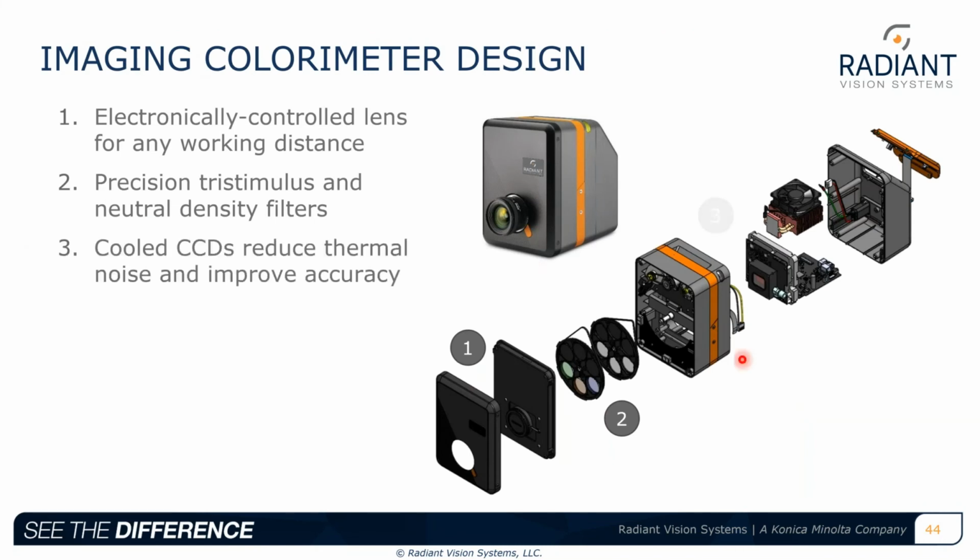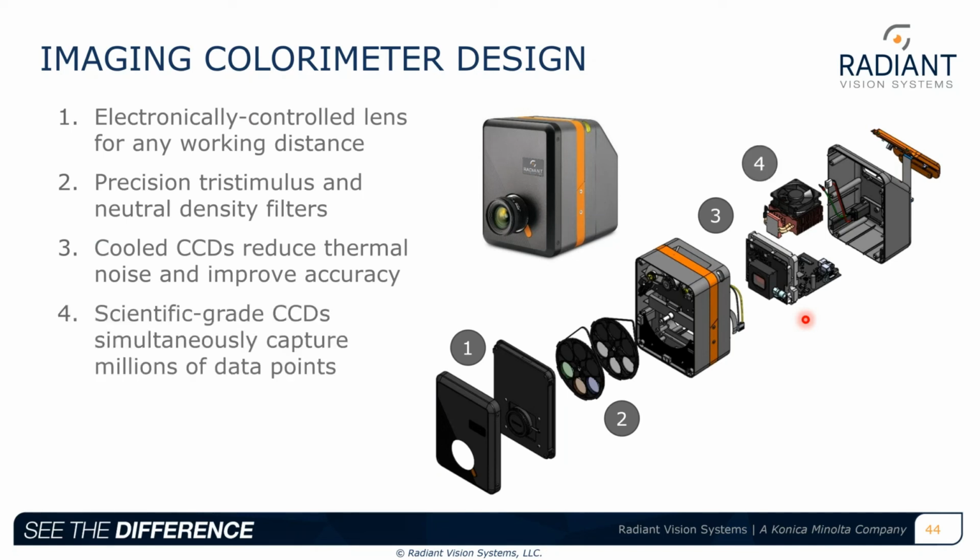So we have the filters and the cooled CCD. At Radiant, we cool and temperature stabilize our CCDs to be at 5 degrees Celsius to help remove noise, as well as performing dark frame calibrations. The scientific grade CCD goes anywhere from 2 megapixels up to 29 megapixels.